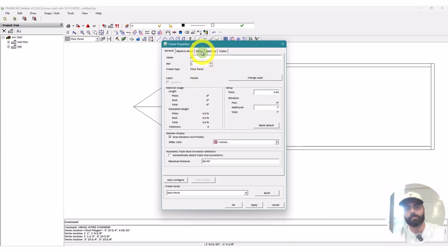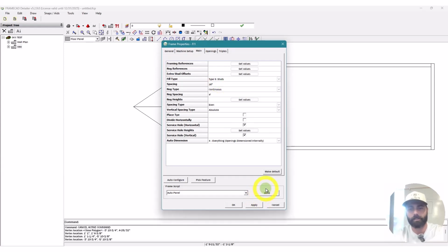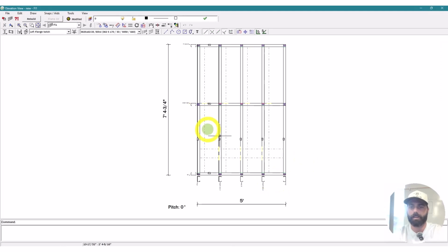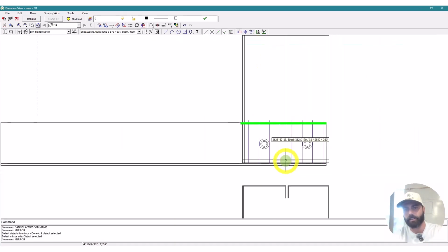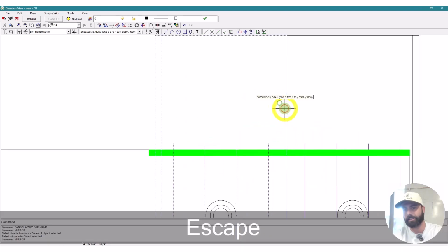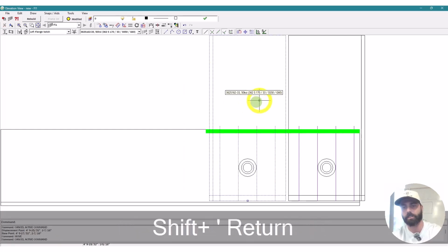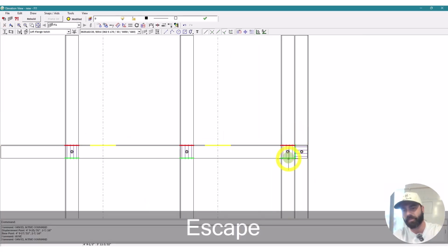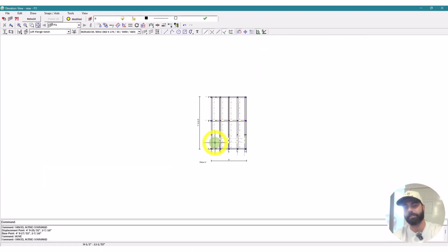Now if this was a loft on the right hand side, we might double this end stud over here. If you're rolling on the machine, you can see how sometimes there's direct contact. It's difficult, so sometimes we'll move this over 1/16 of an inch, so it's easier for the guys in the shop to be able to slide this stud through and then wrap around that stud. So that micro fingernail of tolerance makes quite a bit of difference when you're jumping through the assembly portion. We've got that loft plan.